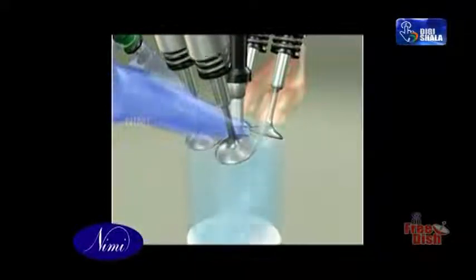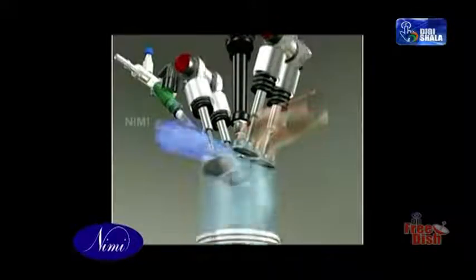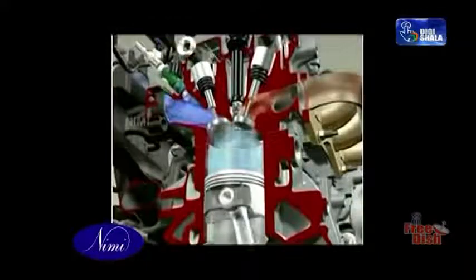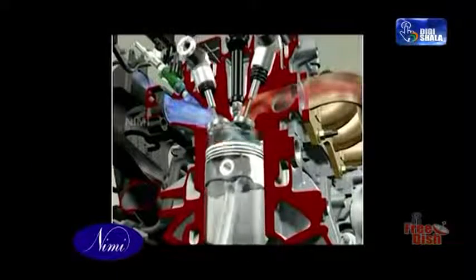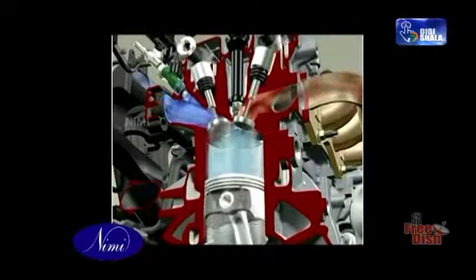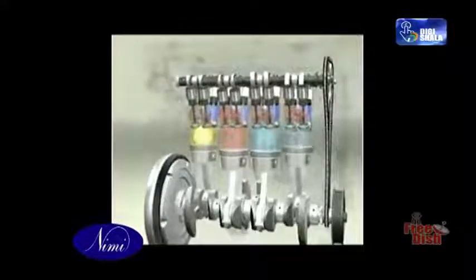Fuel supply. The fuel is special gas oil called DERV, diesel engine road vehicle. It is pumped at very high pressure into the cylinder when the piston is nearing the end of the compression stroke. Power output is controlled by regulating the quantity of fuel injected. Ignition. No electrical spark is necessary since the high temperature of the air in the cylinder is sufficient to fire the fuel oil as it is injected. Engine construction. High cylinder pressure demands a more robust engine construction. A governor is fitted to limit the engine speed to a safe figure.